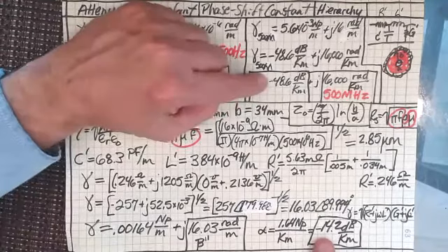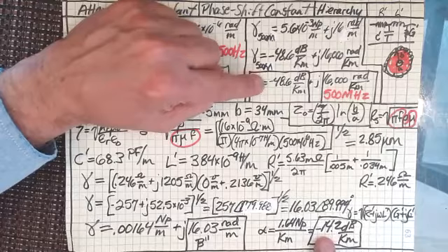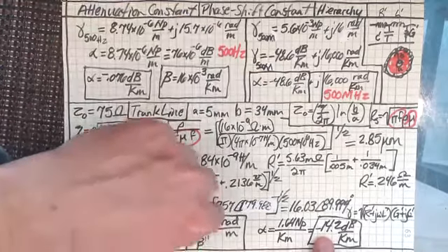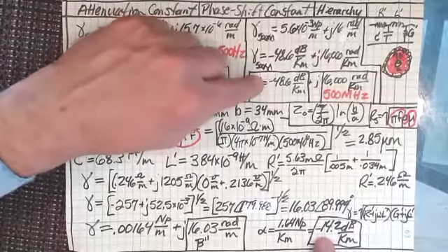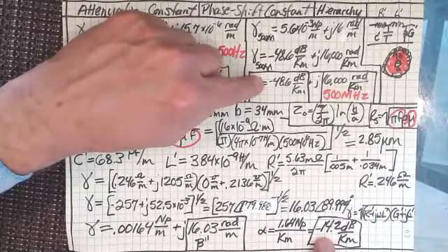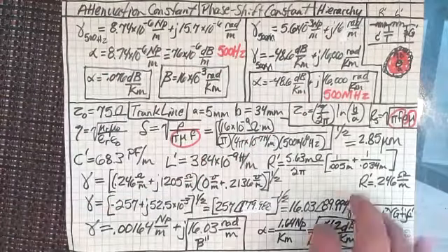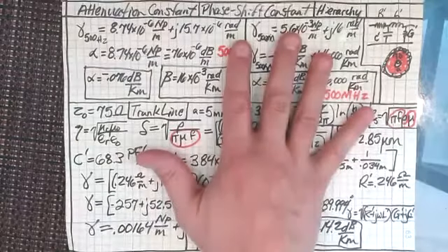Look at that. That's 48. Let's see, 14 times 4. Yeah, it's about 1/4 of the attenuation for those trunk lines that you would get using the same kind behind your house, right? So they use those as broadcast trunk lines, and then of course they come off there with feeder lines to each and everybody's house.